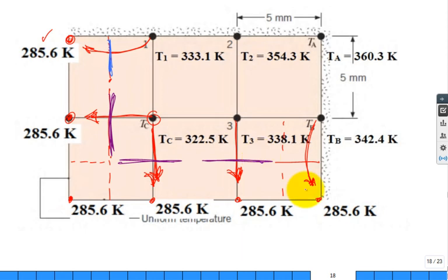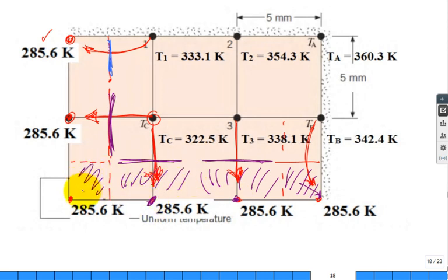What you also have to do is add up the volumetric source. This part gets to that node, this part gets to that node, this part gets to that node, this part gets to that node from the heat source, and that part gets to that node. When you sum up the generation associated with each of those nodes, because that's what's getting to that node, plus the conduction from the interior to each of those nodes, you'll actually get the same value, 6,000 watts per meter. Now, if you keep all your digits on temperatures, it'll even be better.